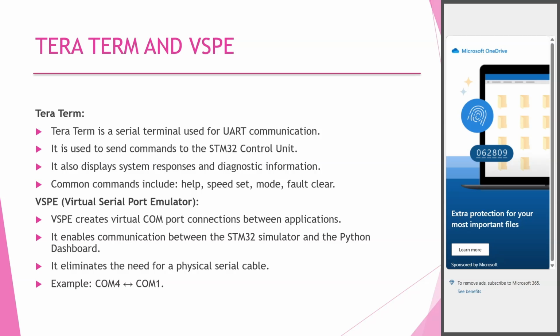Tera Term and VSPA. Tera Term is a serial terminal used for UART communication. It is used to send commands to the STM32 control unit. It also displays system responses and diagnostic information. Common commands include help, speed set, mode, fault, and clear.